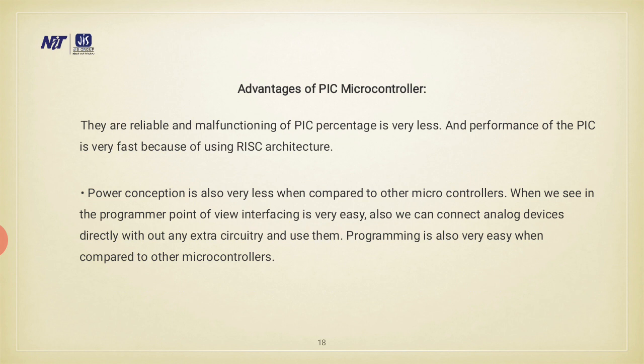Memory: for 8051 it is ROM, SRAM, flash. In case of PIC it is SRAM, flash. In case of AVR it is flash, SRAM, EEPROM. ARM it is flash, SDRAM, EEPROM. ISA: all are RISC features. Memory architecture: 8051 is Von Neumann architecture, PIC is Harvard architecture, AVR is modified Harvard, and ARM is modified Harvard architecture. Power consumption: 8051 average, PIC lowest, AVR low, ARM also low.